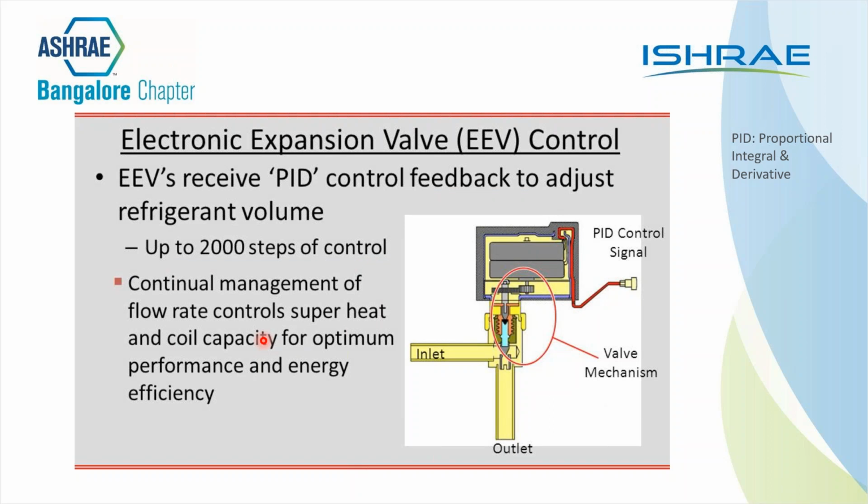Okay. Now, we have got used to a thermostatic expansion valve, which is either always open or always closed, and we call that a valve open in equilibrium. Whereas an electronic expansion valve is never in equilibrium. I would like to explain at this point what an expansion valve does. An expansion valve has 2 names. It is also known as a metering device.